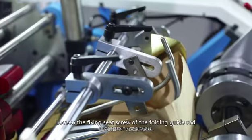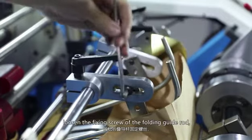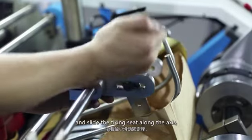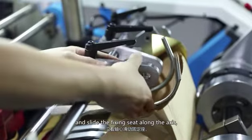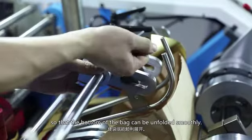Loosen the fixing screw of the folding guide rod. Loosen the fixing seat screw of the folding guide rod and slide the fixing seat along the axis so that the button of the bag can be unfolded smoothly.